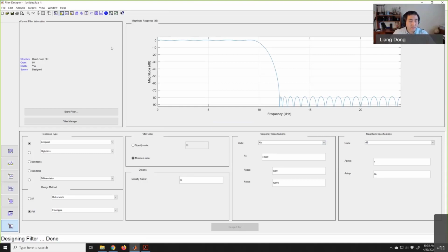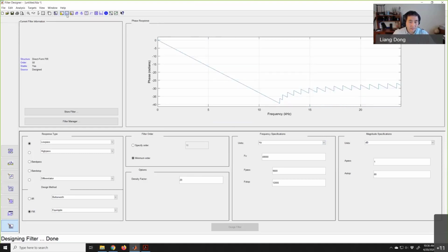And let's look at some other pictures for that. So here I have seen the frequency response of that. This button is for the phase response. Click that. Phase response is linear. Here it goes down in radians linear. In the stop band, it is actually linear. FIR is linear, but you just wrap over pi, wrap over 2 pi.